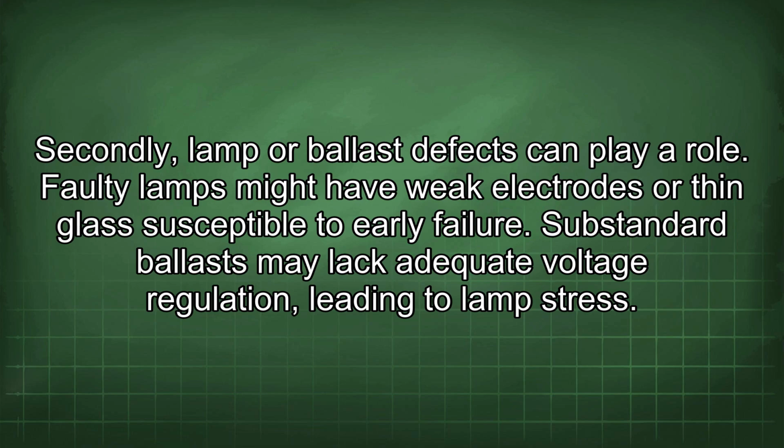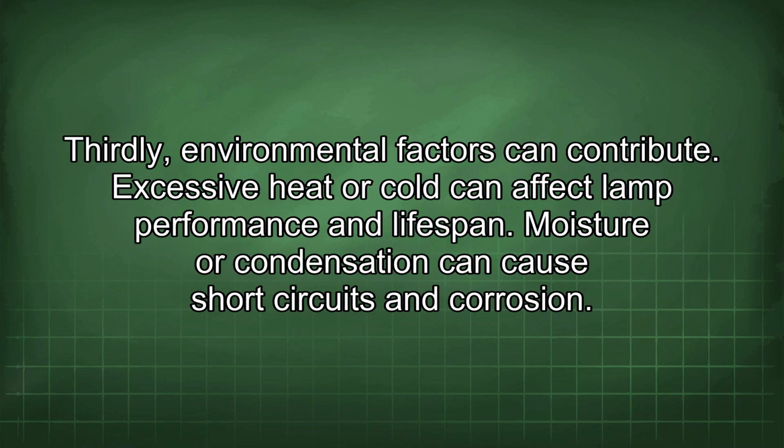Secondly, lamp or ballast defects can play a role. Faulty lamps might have weak electrodes or glass susceptible to early failure. Substandard ballasts may lack adequate voltage regulation, leading to lamp stress. Thirdly, environmental factors can contribute.